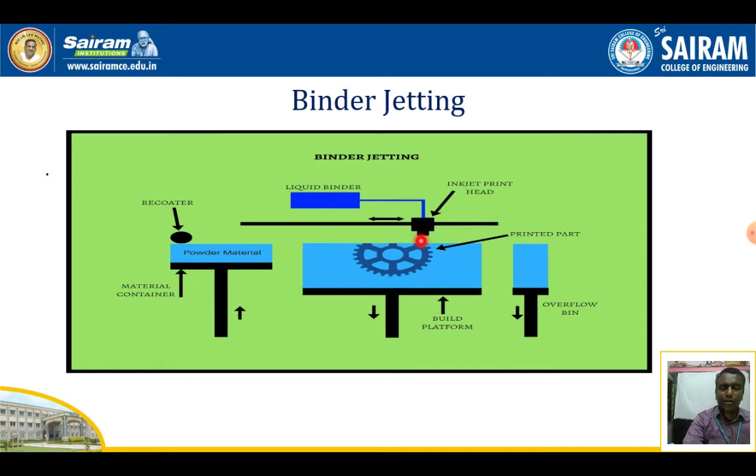The binder adheres to the powder particles. Then the build platform is lowered by a distance equal to the model layer thickness, according to whatever layer thickness we require.